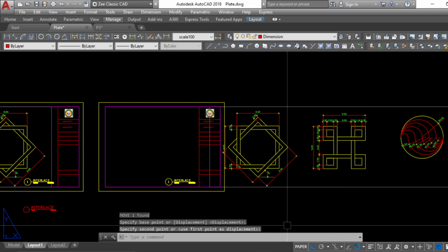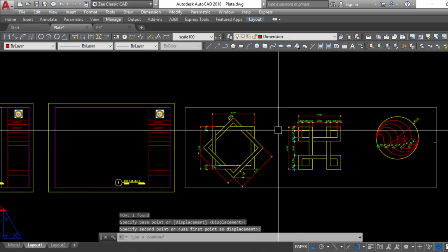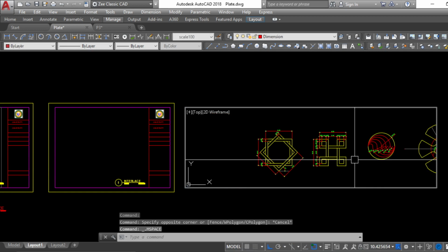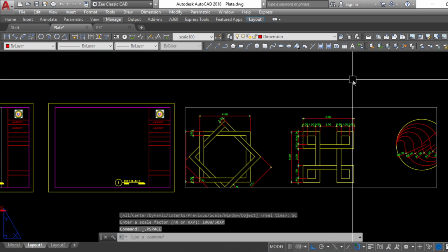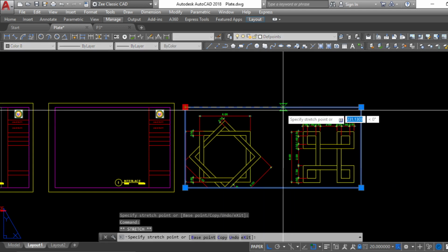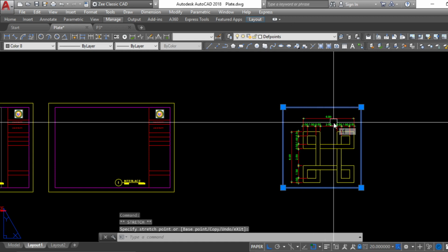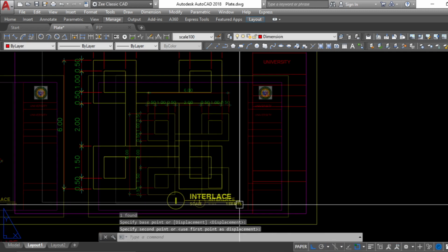For example, this one, what dimension? It's 1:50. So, how do you do a 1:50? Unlock this one, and then re-enter 1,000 over the scale needed, either 100, 50, 700. So, when it's 1:50, it's 1,000 over the scale, 50. Don't forget to execute, enter, and then click outside, lock the viewport. Don't forget to lock the viewport so the model doesn't move. Make sure the viewport is on depth points, and then just move here. Then change this.